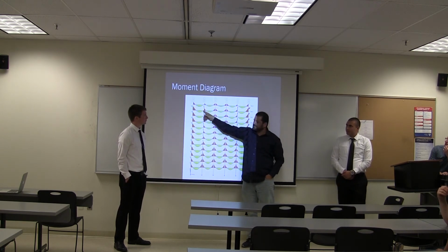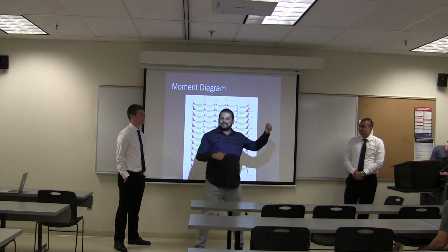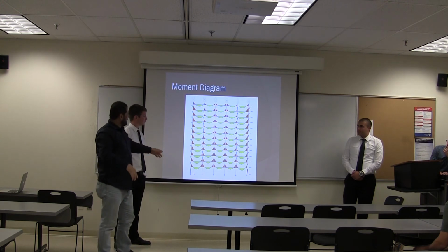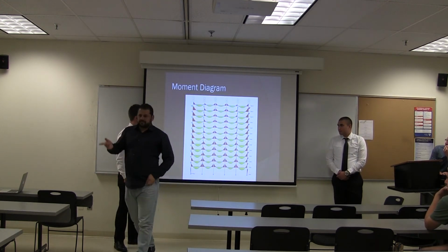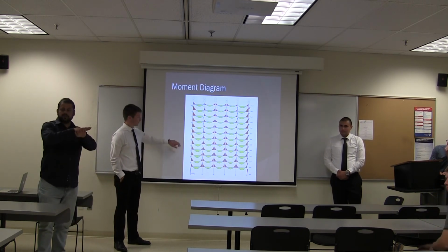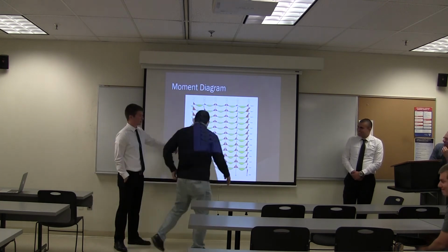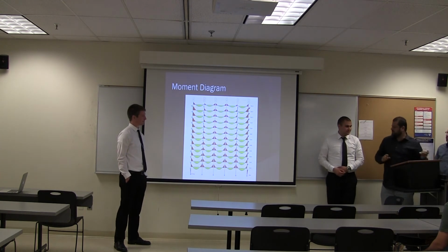If you go to the assignment, end releases, you will see there is a pin in there, missed in there. So you need to make sure it's continuous all the way like what you had in here. So it's actually continuous, not pin, right? The beam is continuous. It should be pin at the end, continuous on the middle over to the outside. You're like, so we were right over. No, you're still missing this concept. It's an easy concept.